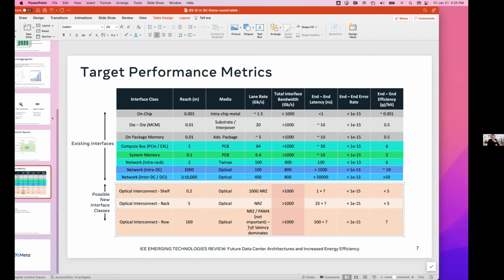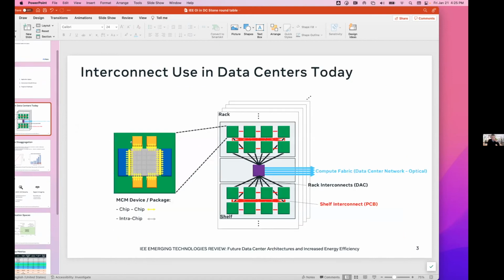I mean, I think Frank, you had a number of really good themes there. I think the first one is if you go back to this picture right here, and I apologize, this is very cartoony, but this could represent a bunch of AOMs on a system meshed together, right? And I think the thesis is, as we go to higher and higher lane speeds, we're already bringing out 128 SerDes pairs on these things. You go to 200 gig, I can no longer put this on a PCB because signal integrity won't let me. So I need another kind of interconnect.